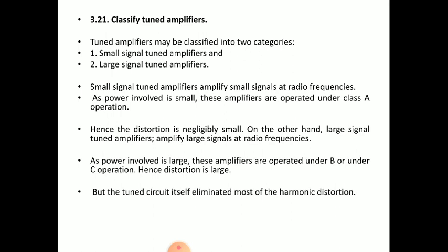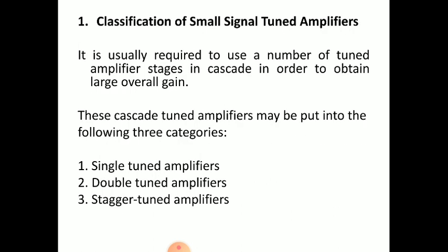Those are called harmonic frequencies of the input signal, which are undesirable. We need only the f value, whatever the input frequency is, it has to be obtained at the output. Because of non-linear characteristics in the circuit, we can get this harmonic distortion, but they are unwanted signals and have to be eliminated.